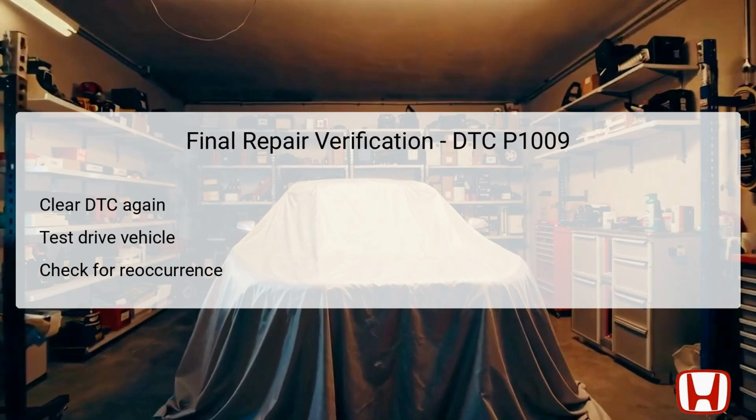After all necessary repairs or replacements related to DTC P1009 have been completed, a final verification step is required to ensure the issue has been resolved successfully. Start by clearing the DTC again using the Honda Diagnostic System, HDS. This action resets the vehicle's onboard system, allowing for a fresh start to monitor for errors.